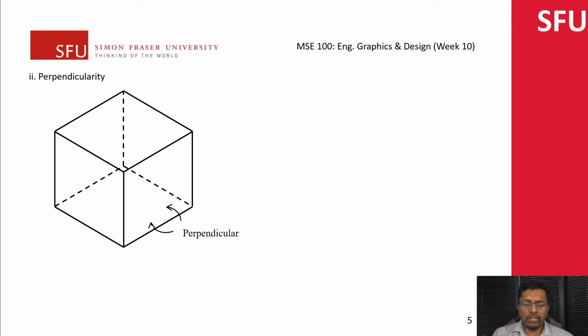So the next tolerance we're going to be looking at is the perpendicularity. So what do we mean by things being perpendicular? They're basically at 90 degrees. Essentially I've defined my theoretical flat surface that we initially had, and then I'm going to have another surface that's going to be perpendicular. The perpendicularity also incorporates any twist, any potential angle that you're going to have in the surface. So when you say perpendicular, you always are going to be saying perpendicular with respect to something.